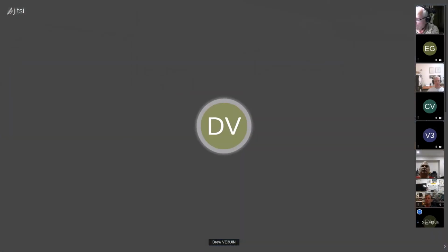I ran into a couple of point of sale kiosk monitors. I think they're 10-inch point of sale monitors, and they're VGA. So you just buy a VGA to HDMI converter, and it'll drive the Pi. The Pi will drive it no problem, so you can put it on any monitor you want.